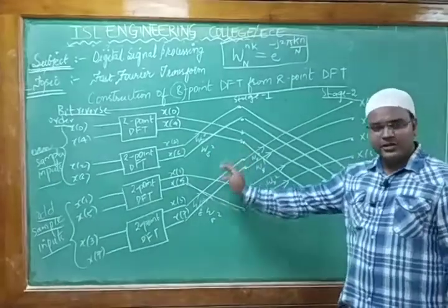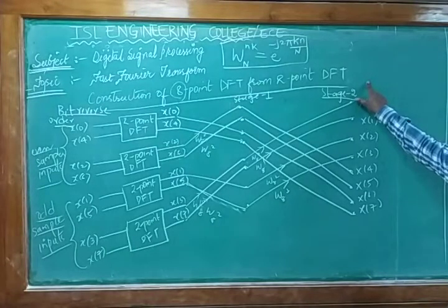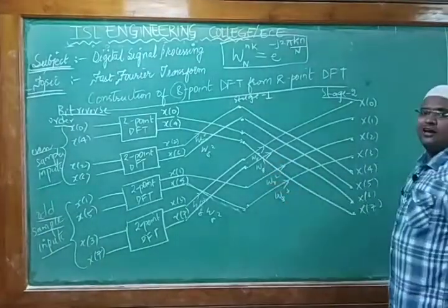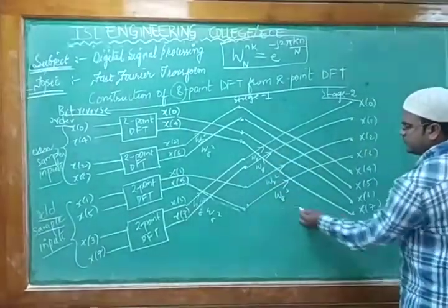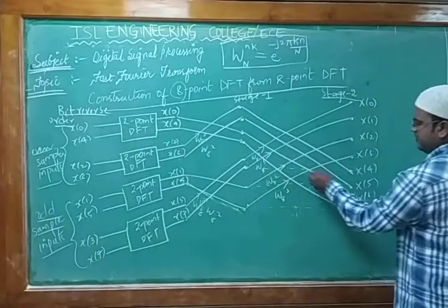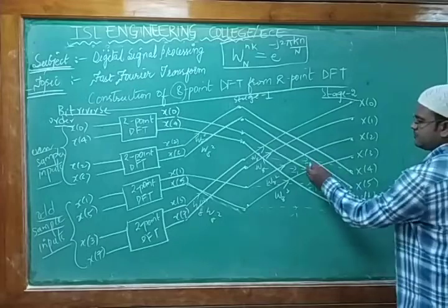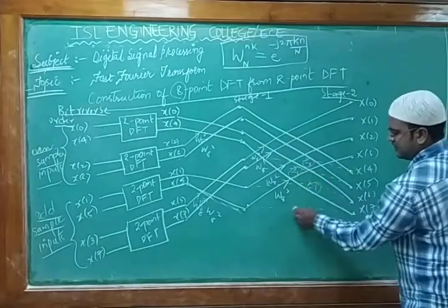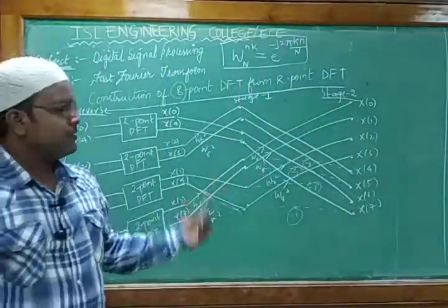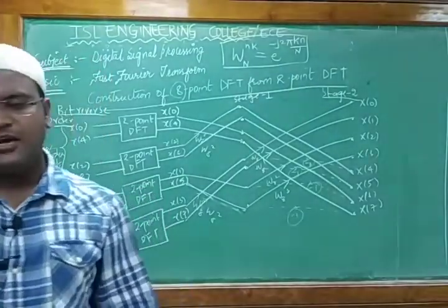After knowing this, we reach the next, the output stage, stage 2, in which we need to mention the output for that particular sequence, and whenever we have feedback, we mention the weighting sequence. And always the feedback should be followed by -1, because whenever we take the values, we mention -1 for solving. Wherever we wrote the weighting sequence, those weighting sequence values should be written as -1. So this -1, this -1, this and this. So this will be the butterfly diagram or the flow graph for designing the 4-point DFT. For the 4-point DFT, we mention it and we design it.